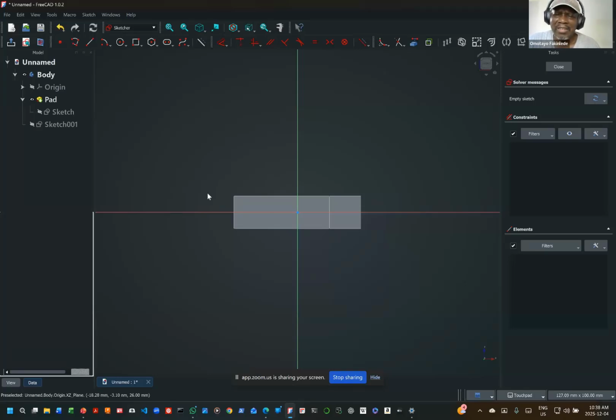One thing that is very useful is that before you start your sketch, it is a good idea to take some reference. You know that the original drawing was fully constrained. So if you take a reference to it, any reference to that fully constrained thing will continue to be fully constrained. So I want to create external geometry. This is the icon that creates external geometry.